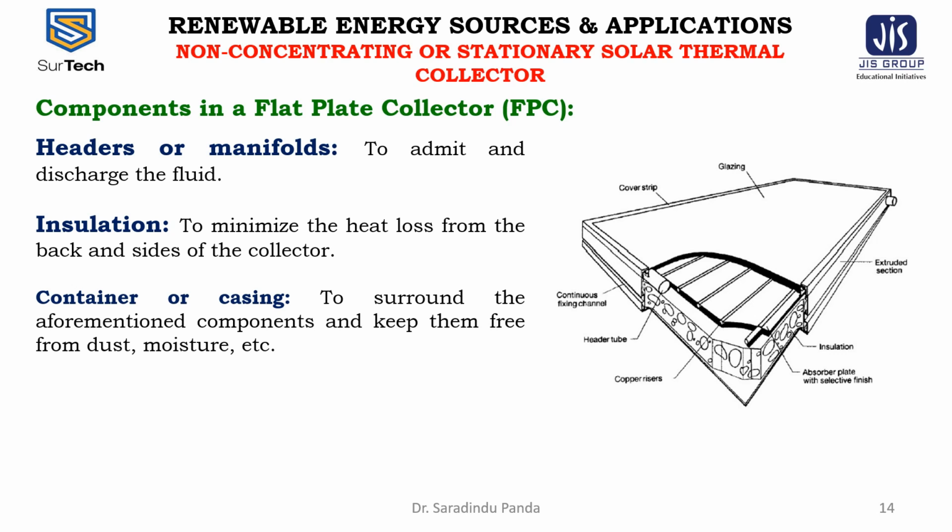The serpentine flat plate collectors differ slightly from the header-riser design. They instead use a single pipe that travels up and down the collector. However, since they cannot be properly drained of water, serpentine flat plate collectors cannot be used in the drain back systems.